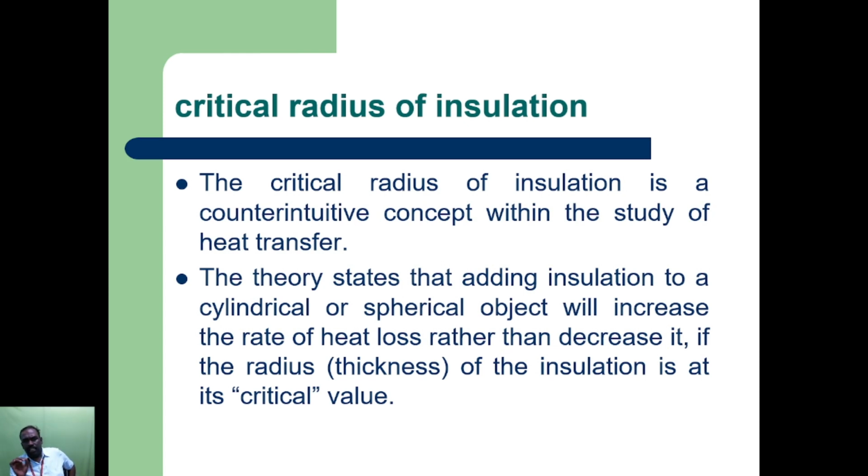What is the meaning of critical radius of insulation? The critical radius of insulation is a counterintuitive concept within the study of heat transfer. The theory states that adding insulation to a cylindrical or spherical object will at first increase the rate of heat loss rather than decrease it, if the radius with the added insulation thickness is below a critical value.